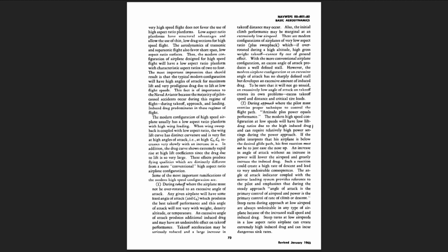Takeoff acceleration may be seriously reduced, and a large increase in takeoff distance may occur. Also, the initial climb performance may be marginal at an excessively low airspeed. There are modern configurations of airplanes of very low aspect ratio, plus sweepback, which if over-rotated during a high altitude, high gross weight takeoff cannot fly out of ground effect.